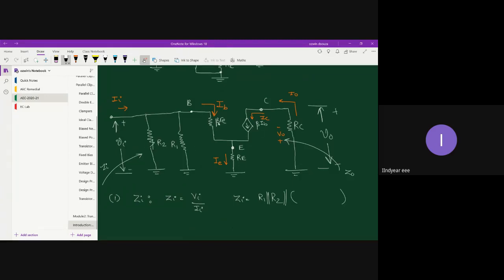On the input side, how are these two connected? Is it mimicking the series connection? Sort of, it gives sort of series connection. But the problem is that in order to claim that beta Re and capital Re are connected in series, you should have the same current flow, right? In case of series circuit, what is the feature?